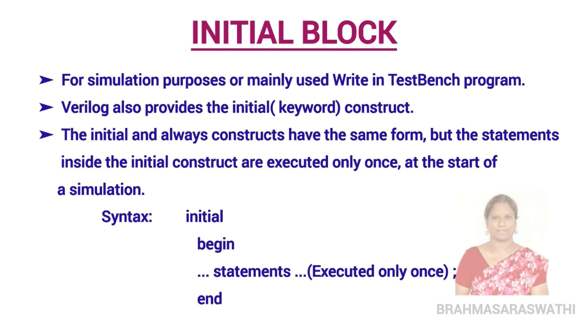But in the initial construct, the statements in the begin and end block are executed only once. If you observe the syntax of the initial block, it starts with initial, next begin. Between the begin and end block, there are statements. These statements are executed only once. This is the syntax of the initial block.